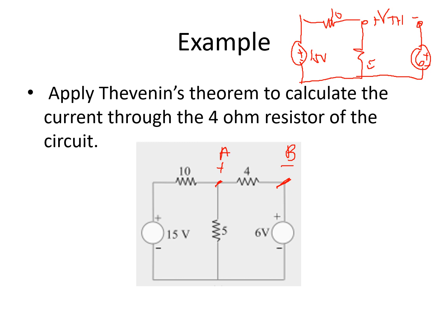Since this is open circuit, we can solve for the current flowing in this first circuit here. We need the voltage across this 5 ohms. So how are you going to determine the voltage across this 5 ohms? We can make use of voltage divider.